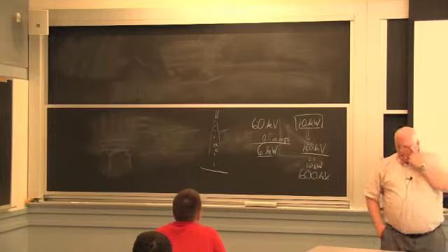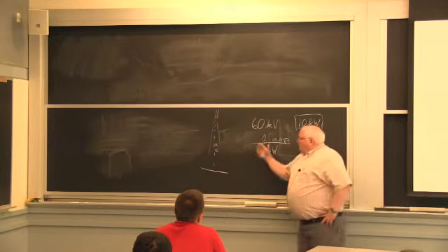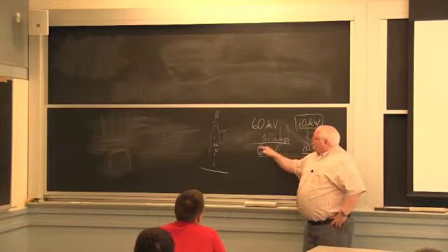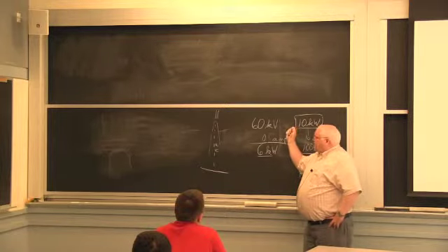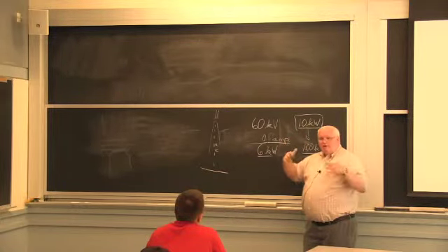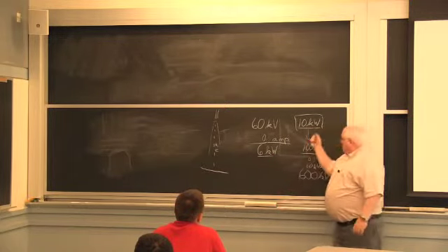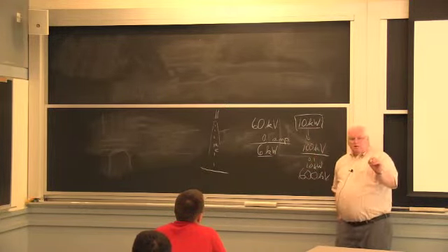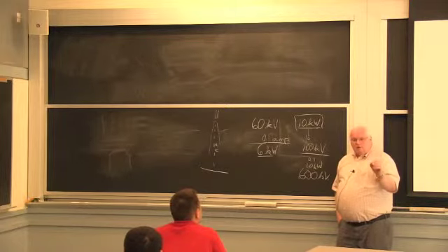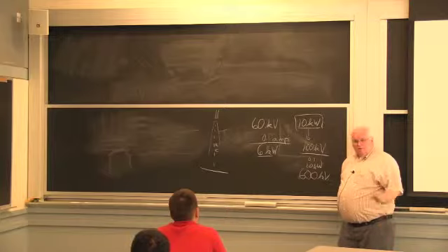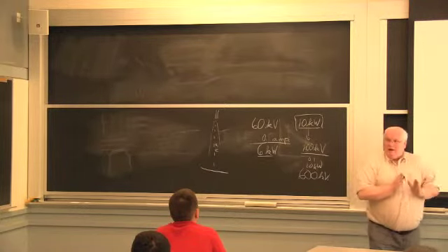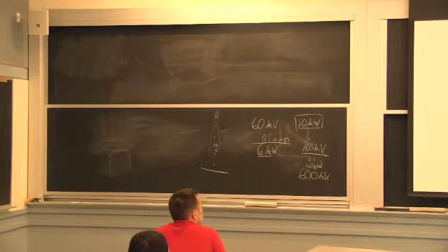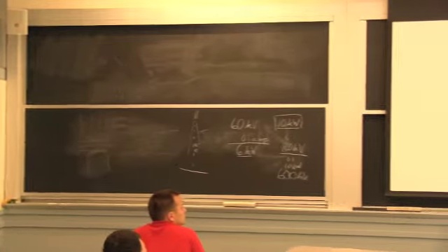Okay, and we'll talk about why that didn't work all that well. But in fact, I have tremendous radiation at the higher voltages, which adds to the cost because I have to have extra lead sheathing. At 100 kilovolts, maybe it's only 1/8 of an inch or 3/16 of an inch of lead. Start getting to 200 kilovolt machines, and now you're talking about 3/8 of an inch of lead sheathing around the whole thing. And if you have windows in the machine, it's got to be leaded glass, and it's got to be several inches thick. Okay, so it just adds to the cost.